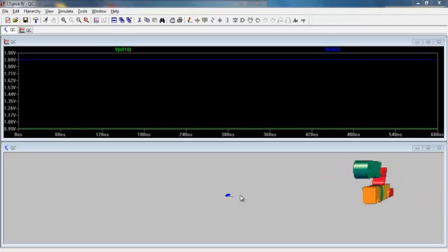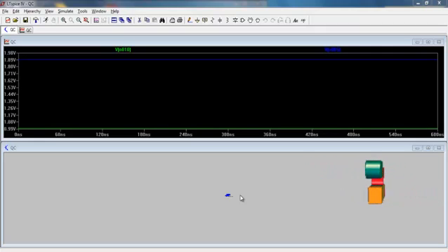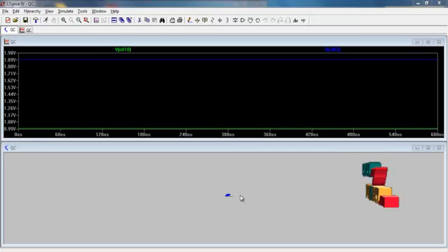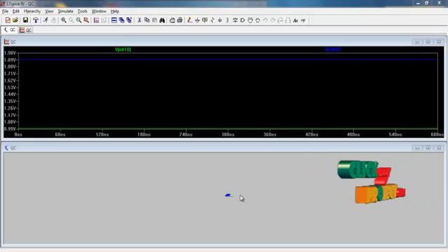The cascode amplifier M3 and M4 is the internal amplifier for enhancing the gain of S32 and the isolation of S23. The inductor L3 not only works as a source degenerator inductor of the internal amplifier to decrease noise, but also features the function of the internal inductor L. It is predictable that the circulator using type 2 BTNs will result in high power consumption and increase the circuit complexity due to the external amplifiers.